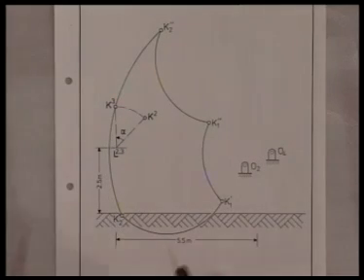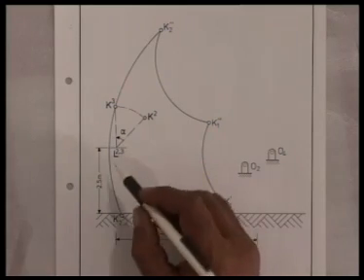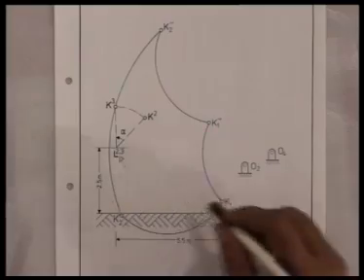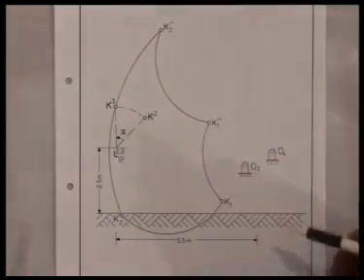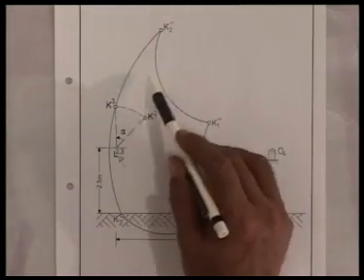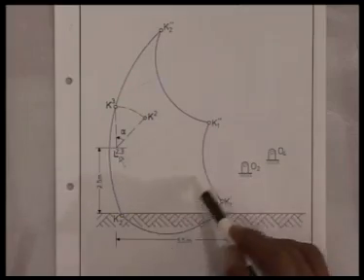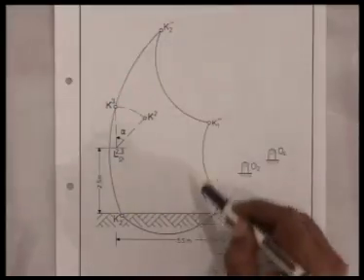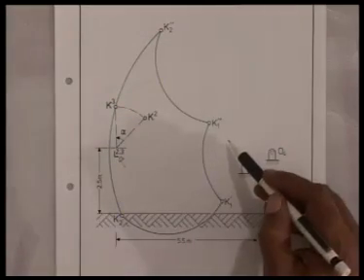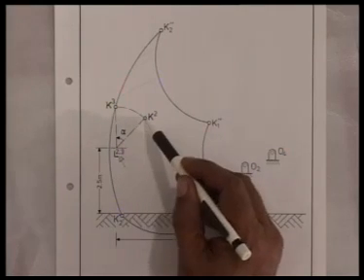To answer the third part of the problem, that is the tilt angle of the bin when the lip is kept at this location L2, we solve it as follows. We have already determined the region in which the hinge K lies when the total range of movements of the actuators is used. The hinge K can never go outside this region consisting of four circular arcs. But L and K are two points on the same rigid body, so their distance cannot change.